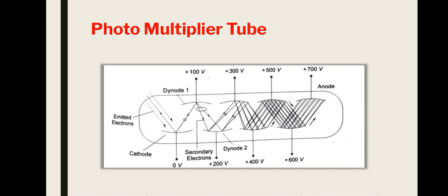The photoconductive material, typically cadmium sulfide, cadmium selenide or cadmium sulfoselenide, is deposited in a zigzag pattern to obtain a desired resistance value and power rating, and is separated from two metal-coated areas acting as electrodes, all on an insulating base such as ceramic. The assembly is enclosed in a metal case with a glass window over the photoconductive material.